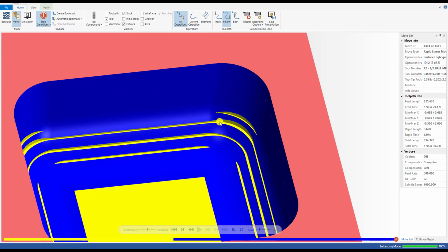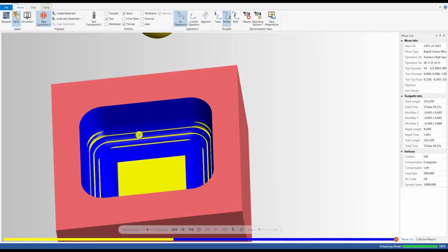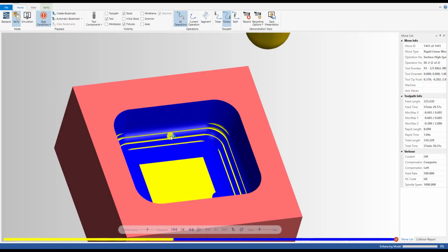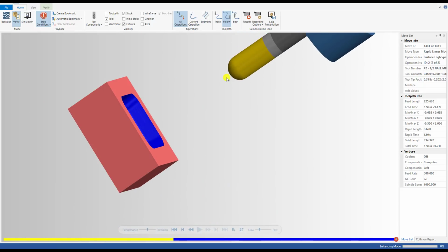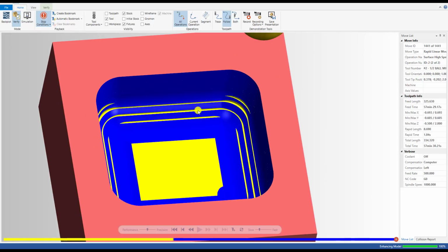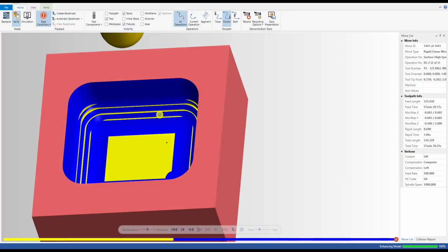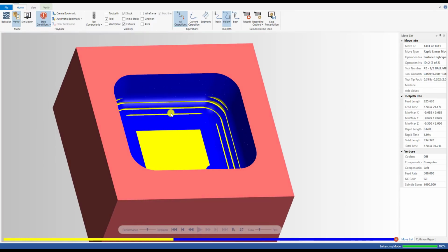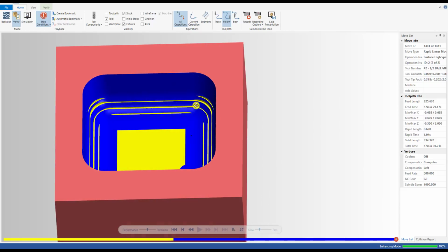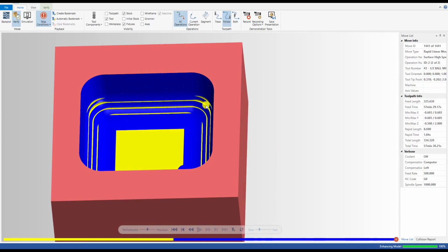And a flat end mill used for the roughing operation has a 0 corner radius, so it can easily contact the fillet here. But it's not the same with the ball mill, so that's why we have this mark here. It's crazy. I'm pretty sure many of you have this issue when you program your part.